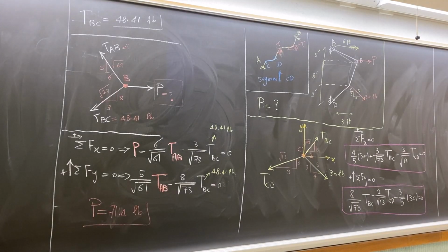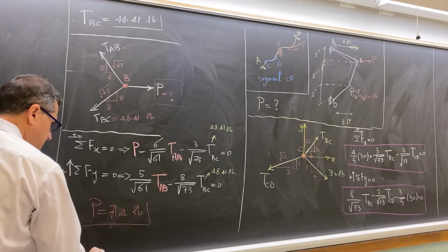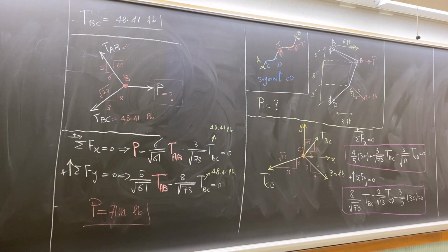So you can see this question was basically statics, and we deal with equations of equilibrium. So when it comes to the cable under concentrated load, this is the method. We just need to draw a free body diagram for each joint and write the equations of equilibrium for each joint, and then try to find the unknown. That is the method. Any question?